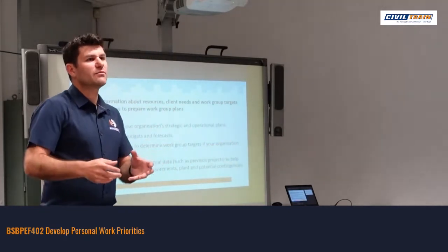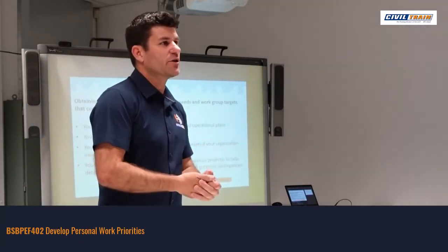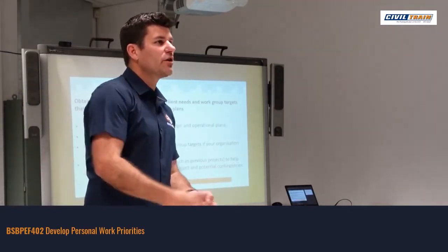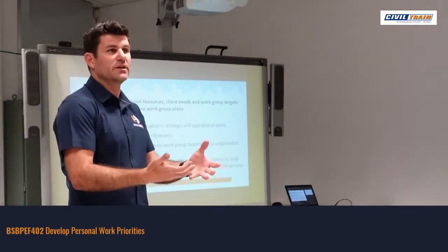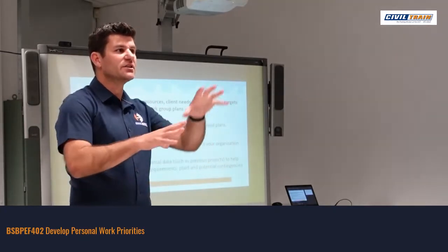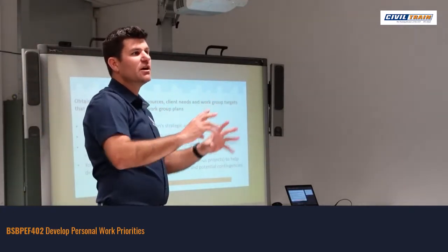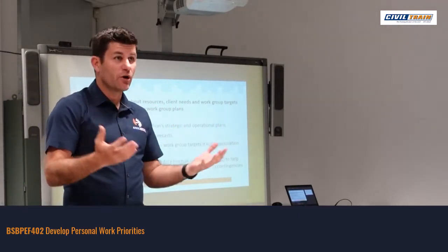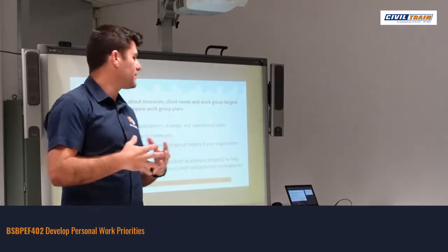But all of a sudden we talk about a dependency, which is something that prevents the next activity from occurring. So obviously if I was going to pour the mud in there, if I didn't have the formwork, I can't pour the mud. So pouring the concrete itself is dependent on the formwork being there. As we get more elaborate with projects and activities, you might find that one task is dependent on a whole range of activities before it can be completed. So that part in itself does need yourselves to really identify what those dependency lines are, to help forward plan for that project.